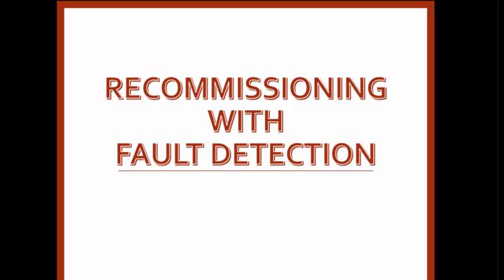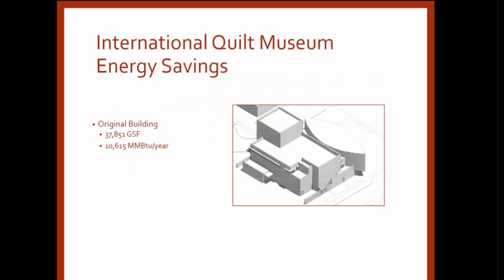So those were the things we were doing before 2015, and we never had an organized recommissioning program for our building equipment. We kept on adding more equipment, more controls, more smarts into our system, but we let it drift a little. So in about 2015, we chose to create a formalized recommissioning program with a goal of recommissioning about 6 buildings a year. And some of the savings that we get from recommissioning, we didn't want to lose to drift again. So at the same time, we also implemented a fault detection and diagnostics program, partnering with Iconics. Some of the results are on the next few slides.